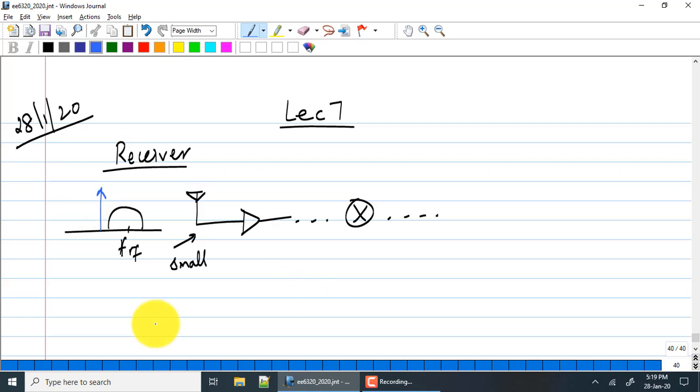The reason is because none of the receivers are so narrowband that they will be selective only to that desired signal. And we will see this when we actually go to RF systems a little bit later on in the course. Most probably once we finish the LNA portion, we'll have enough to do your LNA project. I'll come back to RF systems. The typical kind of frequency selectivity you will need, you are typically operating in the gigahertz range, 2-3 gigahertz range.